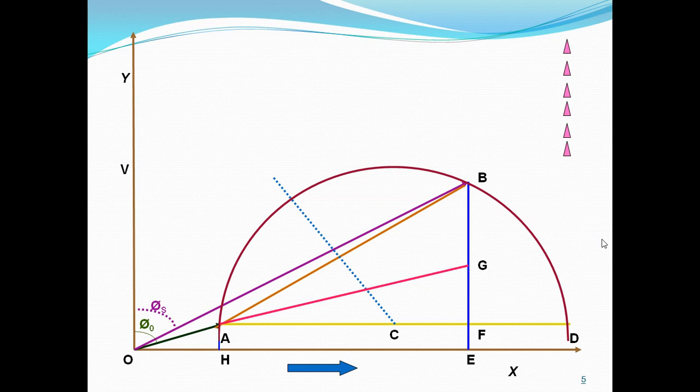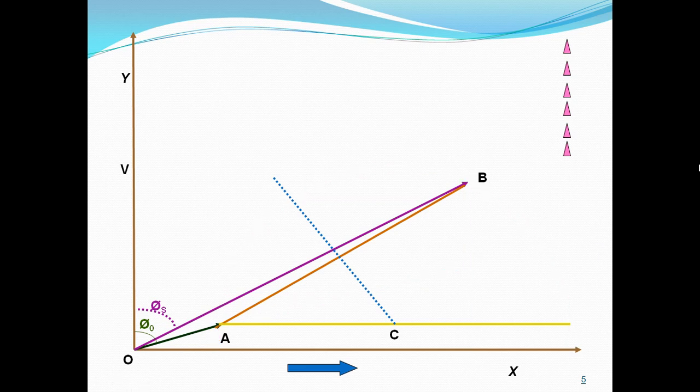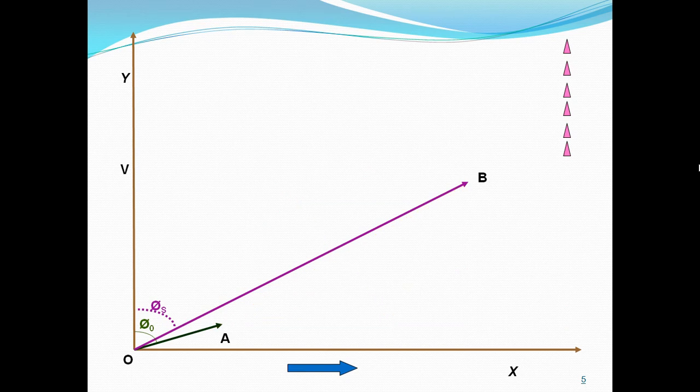Isn is the short circuit current corresponding to normal voltage. So first we have to calculate from the blocked rotor test Isn, that is OB. Isn we have to calculate, that is the short circuit current corresponding to normal voltage.